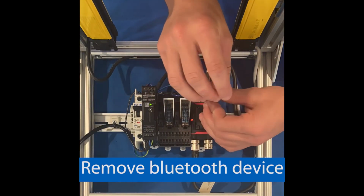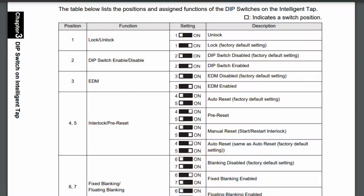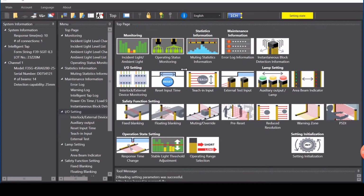So first off, after removing your Bluetooth on your intelligent tap, we're looking at your dip switches on your intelligent tap device. You're going to make sure that dip switch 1 is turned on while the rest of your dip switches are turned off. You can manually disable the EDM function using the dip switches, but for this demonstration, I'm going to show you how to go through the associated program on the PC. Configuration using the dip switches can be found on the product datasheet at automation.omron.com.